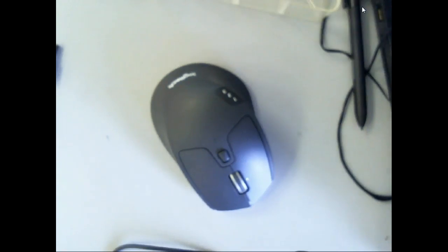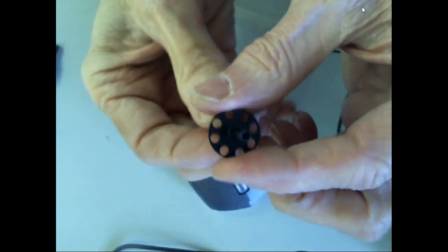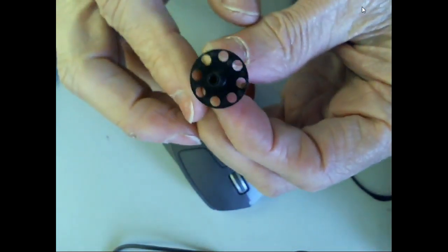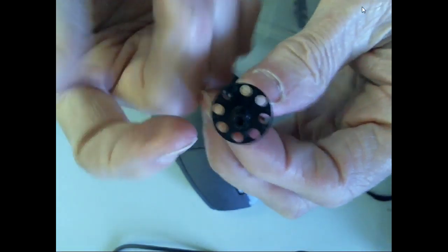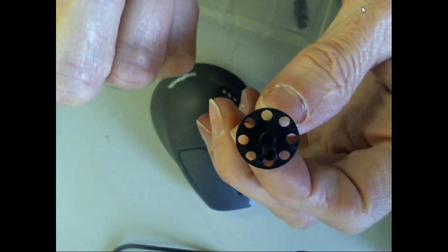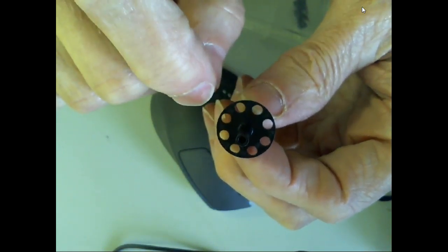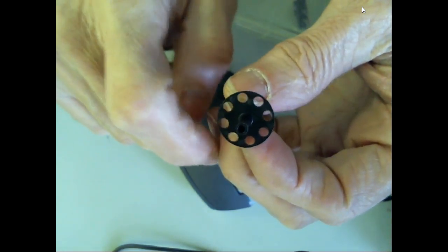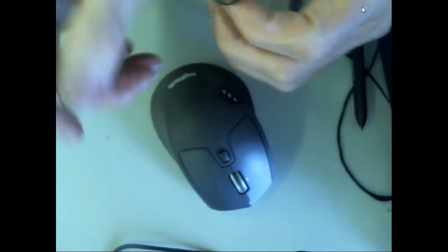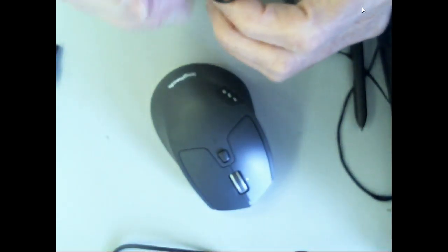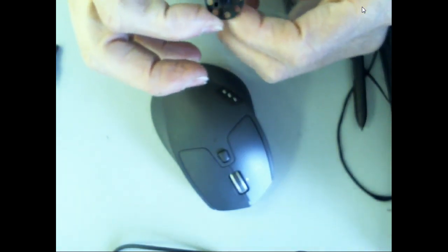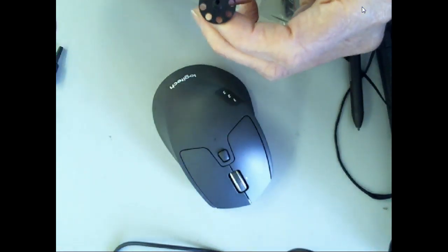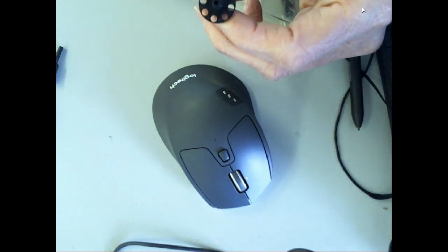Oh, this is my encoder wheel that I was looking at. This would be an incremental encoder. I forgot I had this in my box. So what we do is we use a through the beam, right? We understand that now. The through the beam would shoot through this hole, right? And so with this thing spinning, it would go true, false, true, false, true, false, right? Does that make sense? And then we could use that to sense position, right? What's nice about this, not only can we sense position, we can also sense speed, because the rate of the pulses would give us the speed, and the pulses would tell us the position.